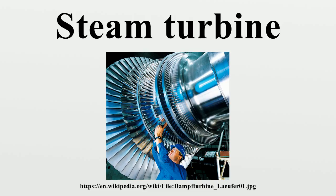Casing or shaft arrangements. These arrangements include single casing, tandem compound and cross-compound turbines. Single casing units are the most basic style, where a single casing and shaft are coupled to a generator. Tandem compound are used where 2 or more casings are directly coupled together to drive a single generator. A cross-compound turbine arrangement features 2 or more shafts not in line driving 2 or more generators that often operate at different speeds. A cross-compound turbine is typically used for many large applications.